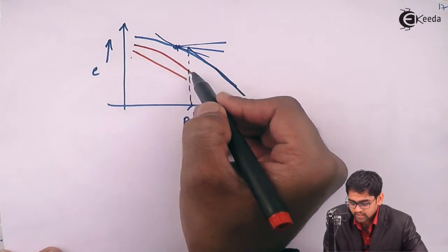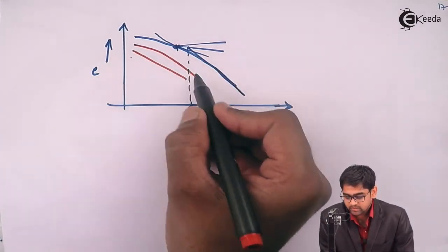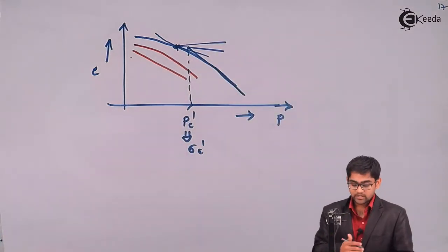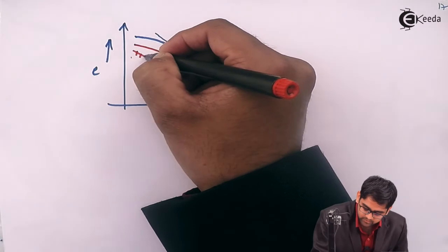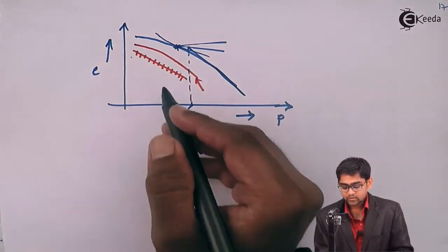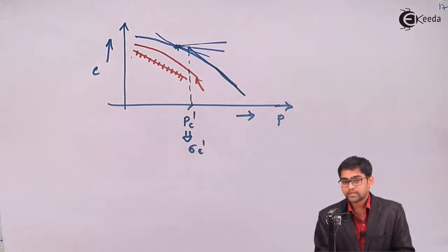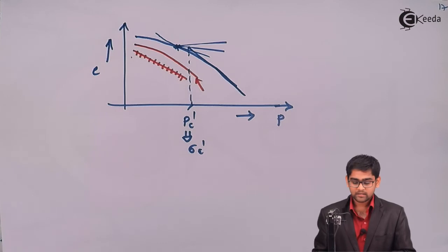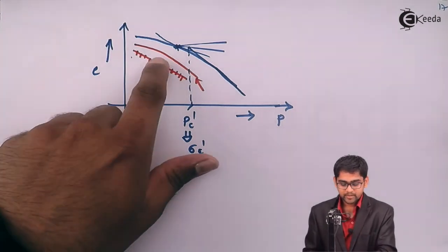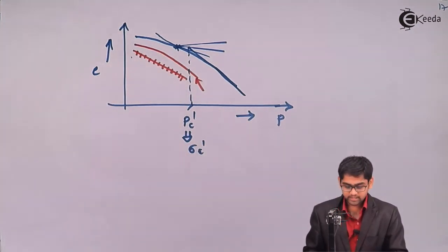And for such kinds of curves, it is not easy for you to determine where the pre-consolidation stress is located. So for such curves, where it is not easy to find the breakup between the recompression and the virgin compression part, Schmertmann gave a smart procedure to locate this particular point where it is equal to the pre-consolidation stress.